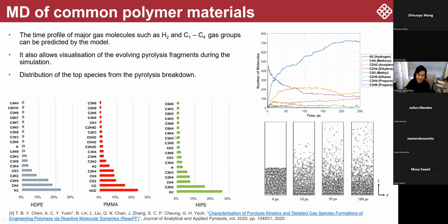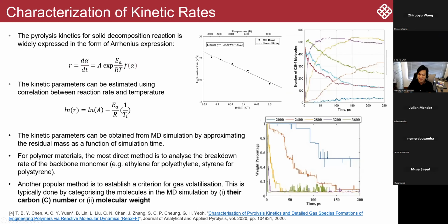And then when it breaks, we can start to look into the detailed spectrum of each of the molecular breakdown process of these polymers. What I want to draw your attention to is the hydrocarbon formation, because once we identify the key hydrocarbons such as methane, propane, and so forth, we can start looking at the flammability limits in detail. But in this case study, because it's more of a validation case study, we want to get something like a TGA response, more precisely the DTG curve.